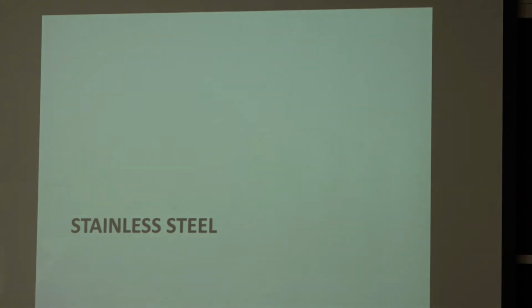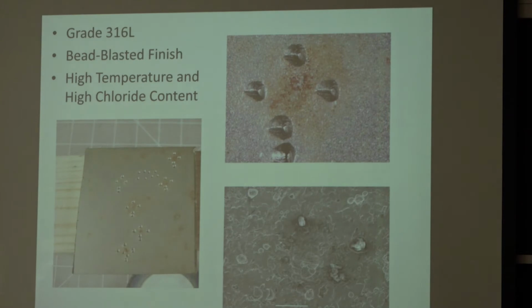Okay, well, stainless steel. Just by the name, it says that it's not stain-free, right? It can corrode. And I don't think I brought really a drastic image of corrosion of stainless. This is because of the topic of today. I can also say that if you put stainless steel in the ground, in soil, there will be conditions going to corrode just as fast, if not a little faster, than carbon steel. And those conditions are when you lose the stability of that same surface passive layer.